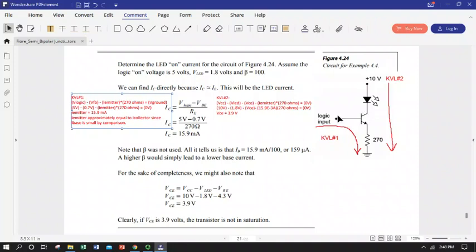So there's a lot of ways that we can relate the voltage at the base to the voltage at either the collector or emitter and create a bit of a relationship between them. So we create a little bit of a feedback scenario, which can be super useful.